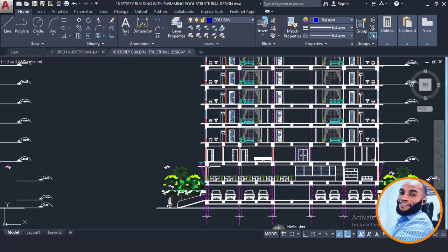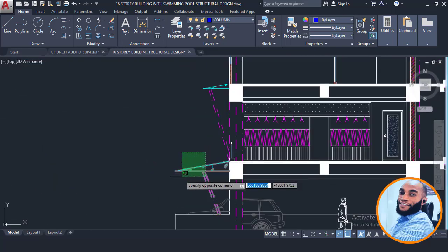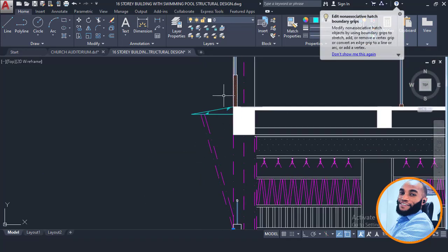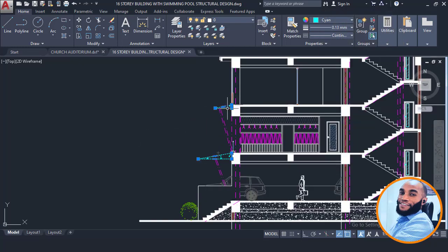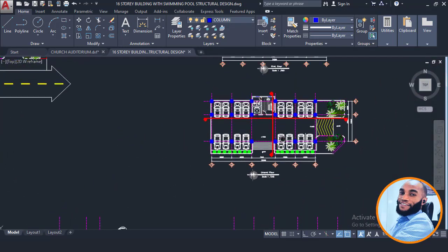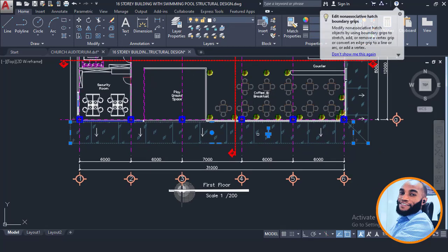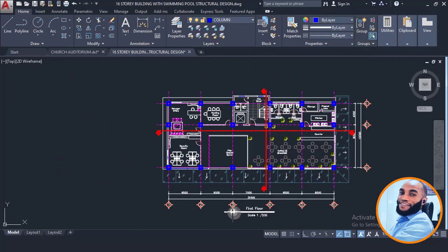What is that? On this place, this tells me that this is basically the canopy here. I can see that they have the same symbol. So this is a canopy, which can be either a plastic canopy and the like. Knowing that this is a canopy, I can choose to remove it from my structural modeling. I will not consider this when I'm trying to model my structure, because it can have an independent member that carries it separately. Now again I'll ask, what is the next thing here?